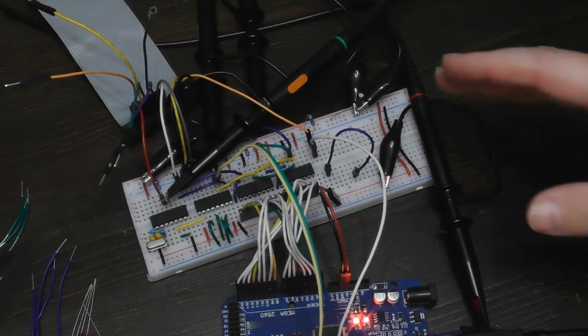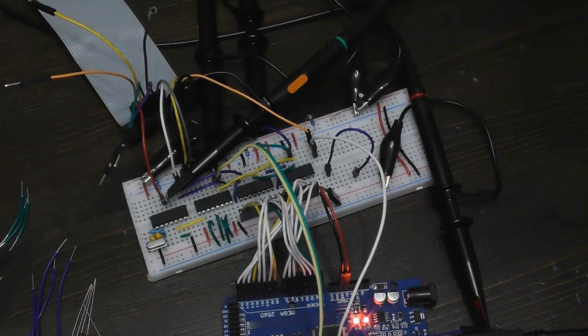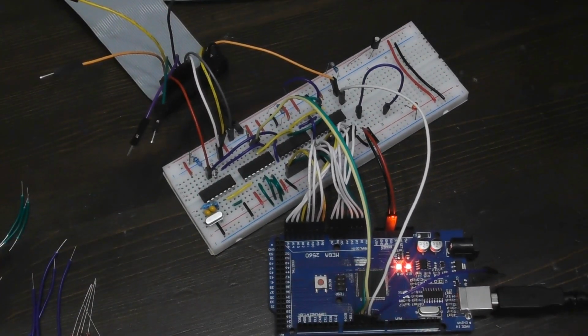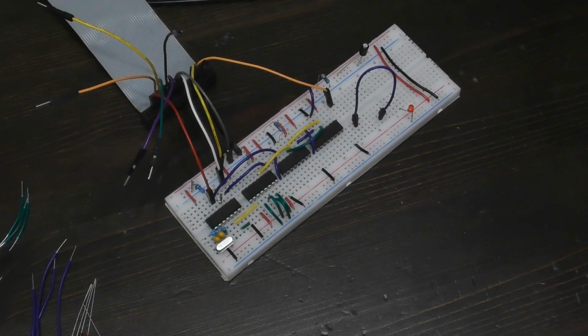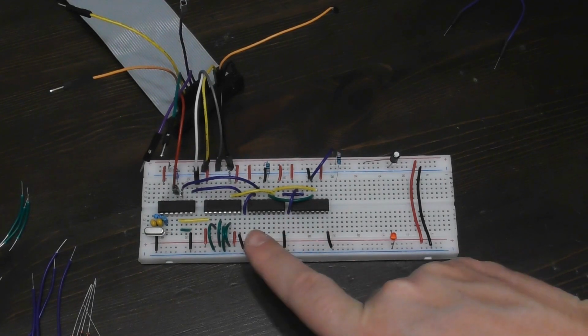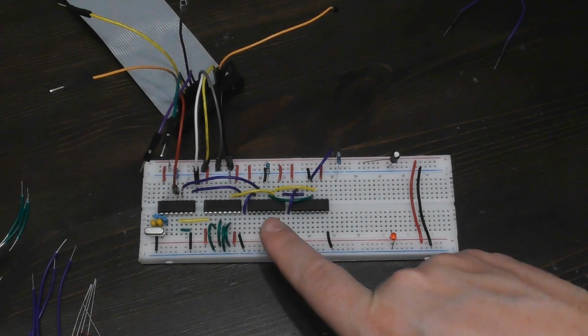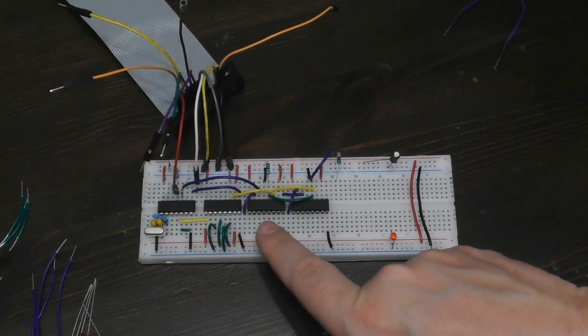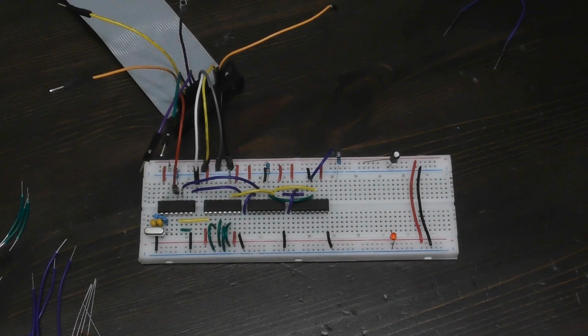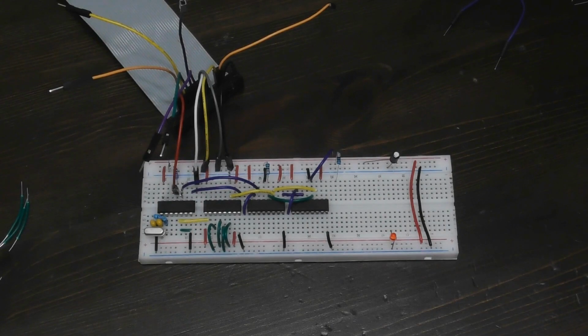So here's the circuit from the last video. Let's disconnect the scope and the Arduino and then start putting the new components in. So here are the shift registers, the 595s, and I think I decided I want to take clock bits 0, 1 and 2 and data bit 5, which was probably somewhere over here. And these are the pins I want to check for zeros on in order to start triggering my byte synchronization circuit. So I don't actually have a 4 input OR gate.